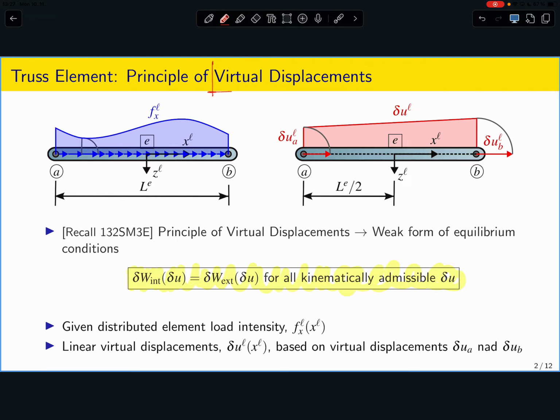And the setup is as follows. You basically assume that you have some isolated element taken out of the structure, as shown here. In this particular case, I'm considering only truss elements in my analysis, meaning it's pin connected at both ends. Hence, it can sustain only axial loading, and can carry only the load which is distributed in a way that is aligned with the element.